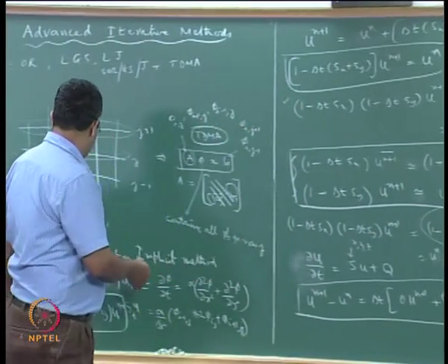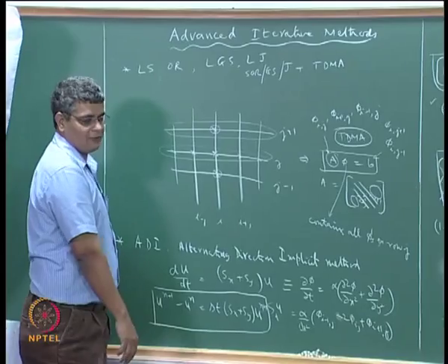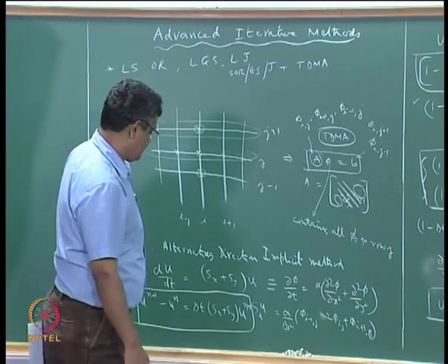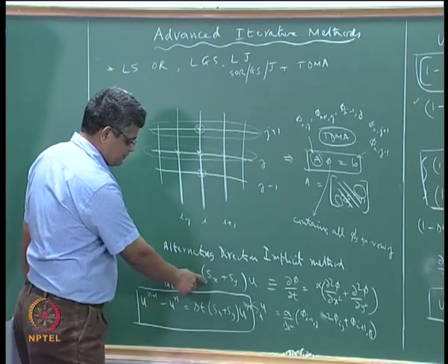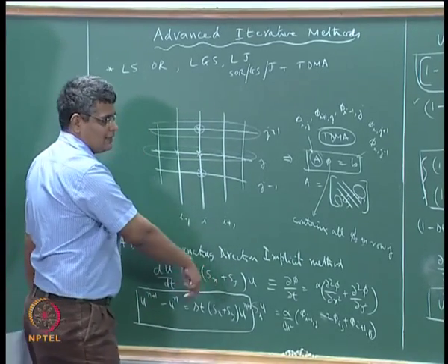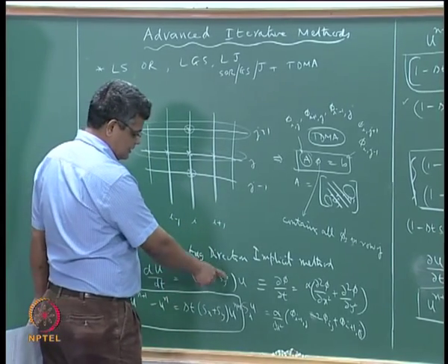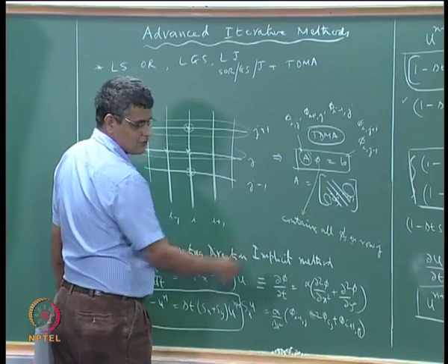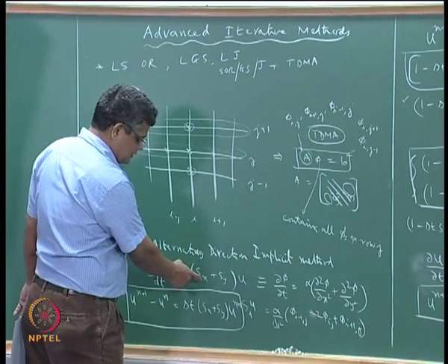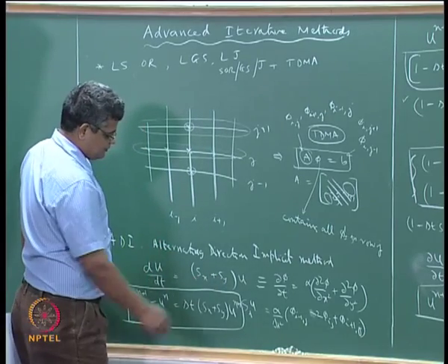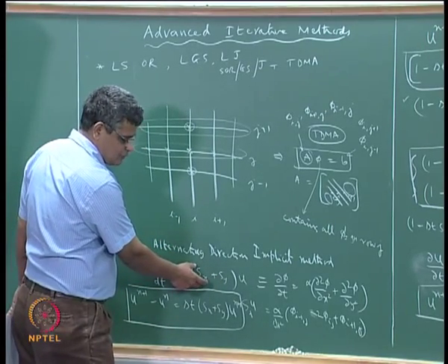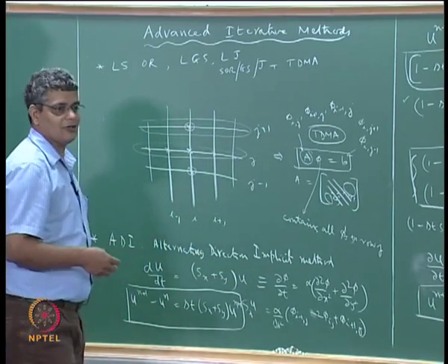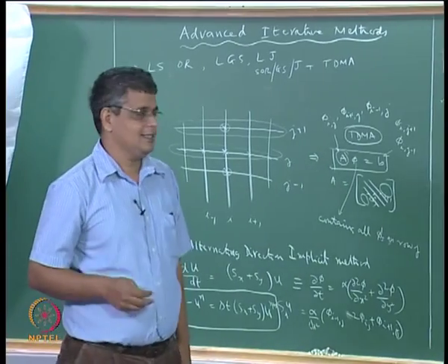Although we have described this for an unsteady equation, the ADI method can also be used for steady state equations, in which case the unsteady term will not be there, but you still have Sx and Sy and Sz. So in such a case again this will be converted into A phi equal to b involving the diagonals coming from here and here. So we can split it up again into diagonals coming only from the x derivative, only from the y derivative, only from the z derivative. So this method can also be used to solve steady type of equations.